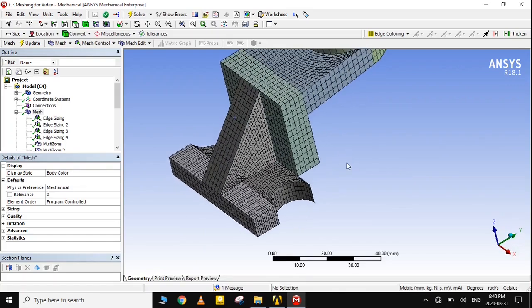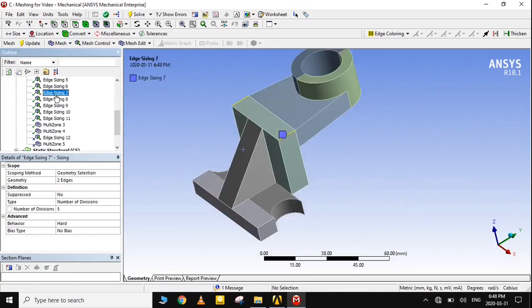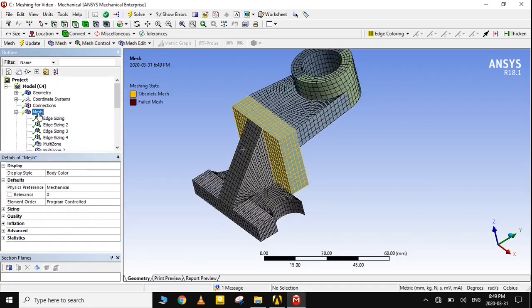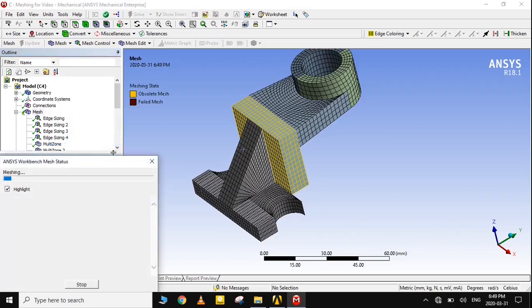The advantage of structured mesh is that we can increase or decrease mesh elements' size in any area of the geometry and save computational power. Also, mesh independence is generally achieved faster in structured meshing.